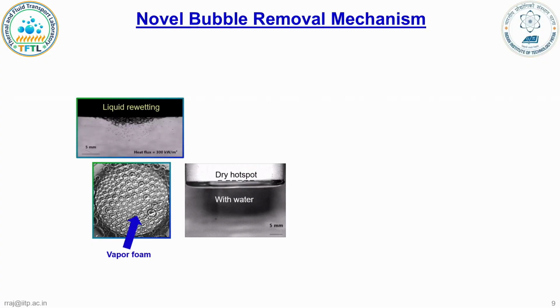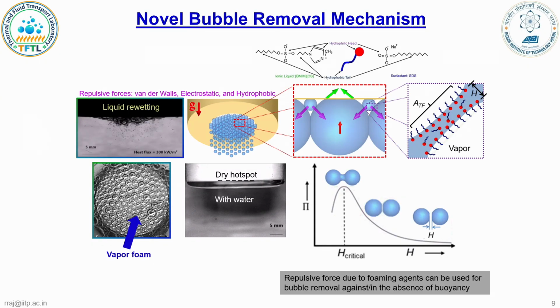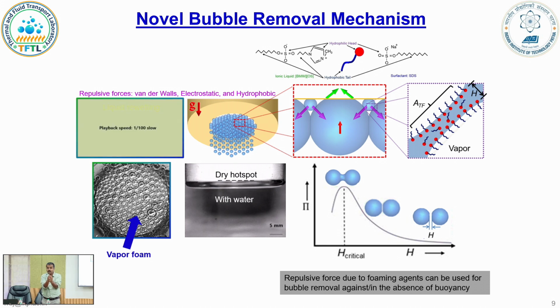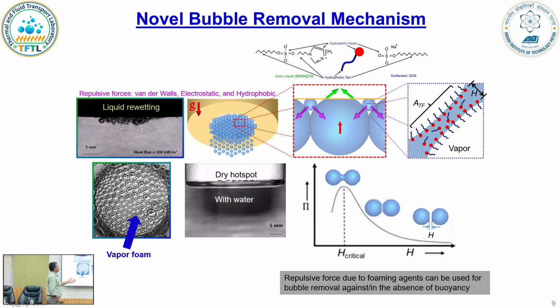So what's pushing them down is very simple. Imagine a big bubble which has nucleated another bubble. Now since this is a foaming solution, these bubbles do not coalesce. Their interfaces do not come together to form a bigger bubble, and that's not a thermodynamically energy favorable process. Now in between the liquid you have another nucleation, and all of us know any bubble initially in the inertial growth regime grows very fast. So the rate of change of this diameter is much more than this, and essentially they pull all around the periphery. There are smaller nucleating bubbles.